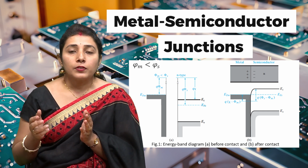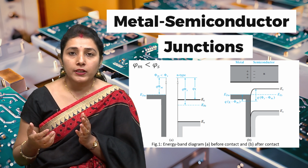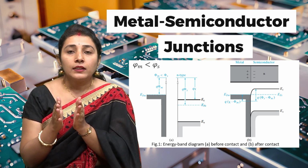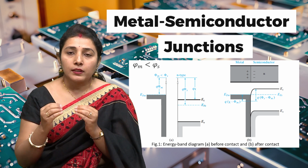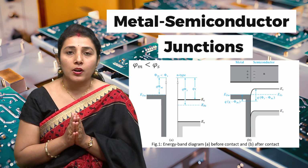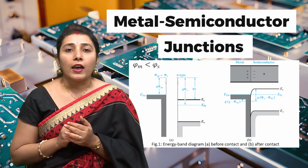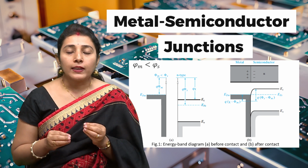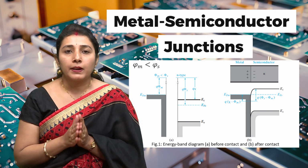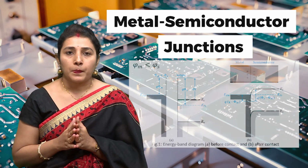The electrons from the n-type semiconductor, where electrons are the majority carriers, come to the metal-semiconductor junction, and hence the Fermi energy level is aligned for the metal and the semiconductor, forming an ohmic contact. So for an n-type semiconductor to have an ohmic contact, phi m must be less than phi s. The work function of the metal should be less than the work function of silicon.